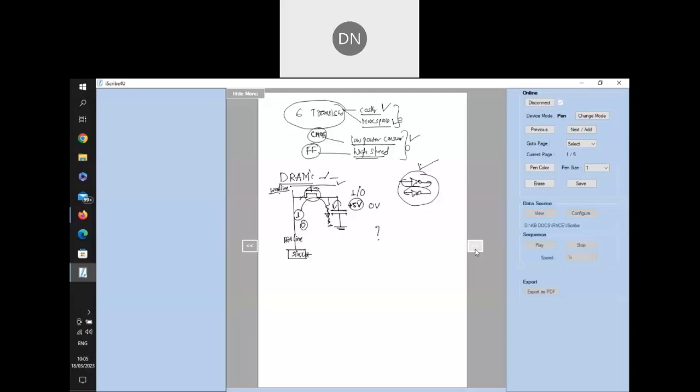So these are the two places where it will discharge. After some time, let's say 60 milliseconds, 30 milliseconds, the data inside, which was plus 5 volts, keeps on reducing. It becomes plus 4 volts, 3.3 volts, and at some point 2 volts. When it reaches 2 volts, it is not considered as 1. Anything from 2.8 volts to 5 volts we consider as logic 1. When it reaches below 2 volts, it is changing the state from 1 to 0, so it is losing the data. So what should we do?